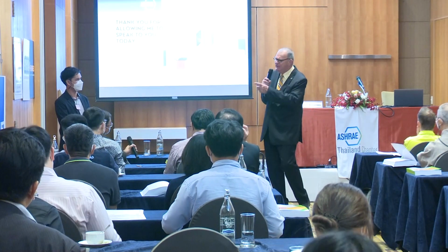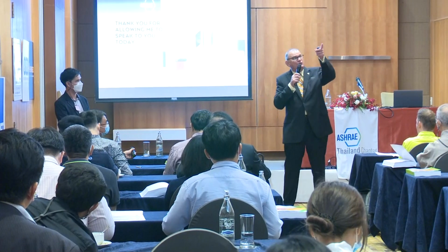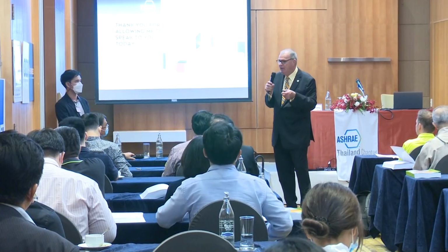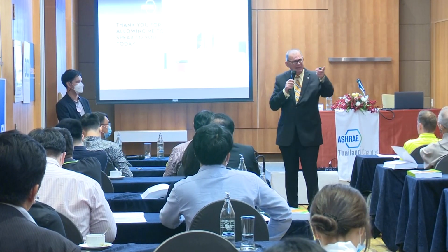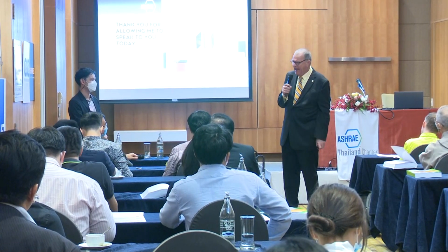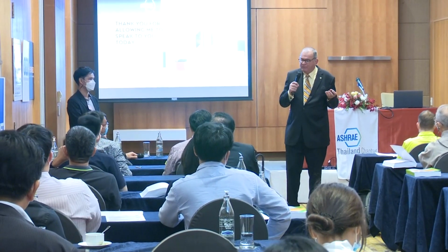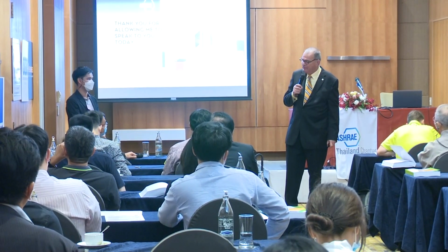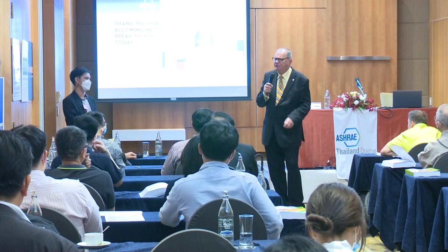These airflow monitors are installed in locations that you have to get up on a 10-foot ladder to get to and to clean. You think a maintenance guy is going to climb a ladder and do that? It's just not happening. People think that's happening. It's just not. And they say, oh, well, filters cost a lot.